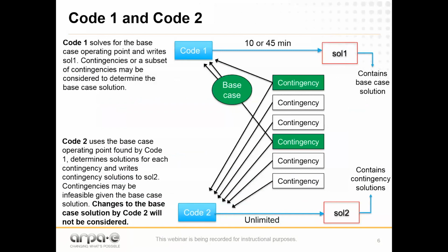The intent behind giving you a Code 1 and a Code 2 is that there are contingencies that very well are easy to handle. In existing practice in industry, contingency screening occurs. Before you solve a security constraint unit commitment at the day-ahead time stage, or a security constraint OPF, or a security constraint economic dispatch, there is a down select of what constraints and variables to model. There is a down select as to what contingencies to model. That's what goes into the optimization engine.